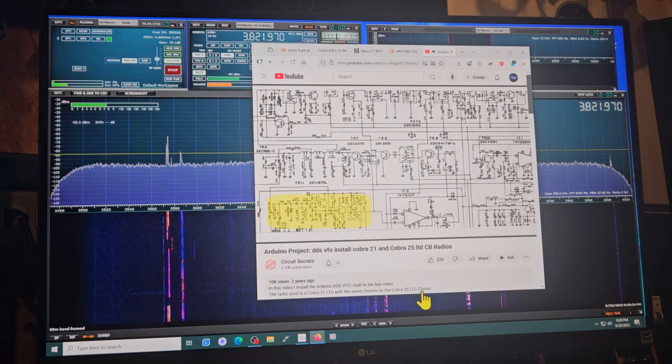This is the VCO in the schematic. This is the transmit mixer chip, which performs direct mixing for the transmit carrier. This section is the receive circuit, which mixes down to the 455 kHz intermediate frequency indirectly in stages. These stages are sets of FETs and IF transformers calibrated with capacitors and adjusted to only pass part of the signal, or an intermediate frequency.